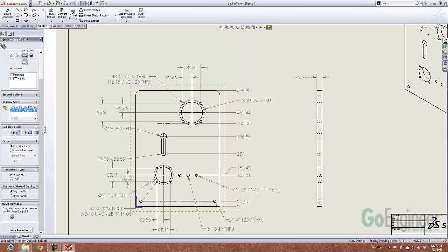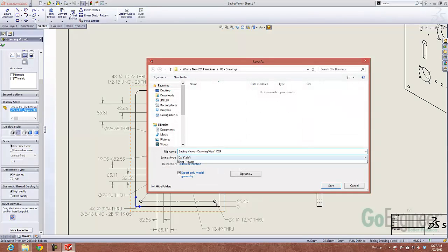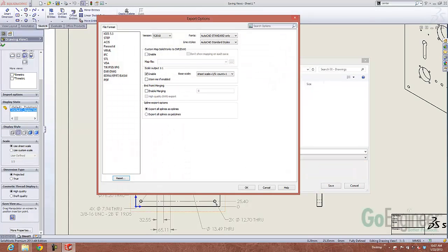Now you can save this view with a different coordinate system. So where is 0? That's what this little blue arrow is indicating. And then when I hit the Save button, this will allow me to save this off as a DXF or a DWG. We of course have all the traditional options. What version? We'll go all the way back to version 12 of the DXF, for example, and enable the one-to-one output. So in the view that I'm saving off of the DXF, it will be one-to-one.